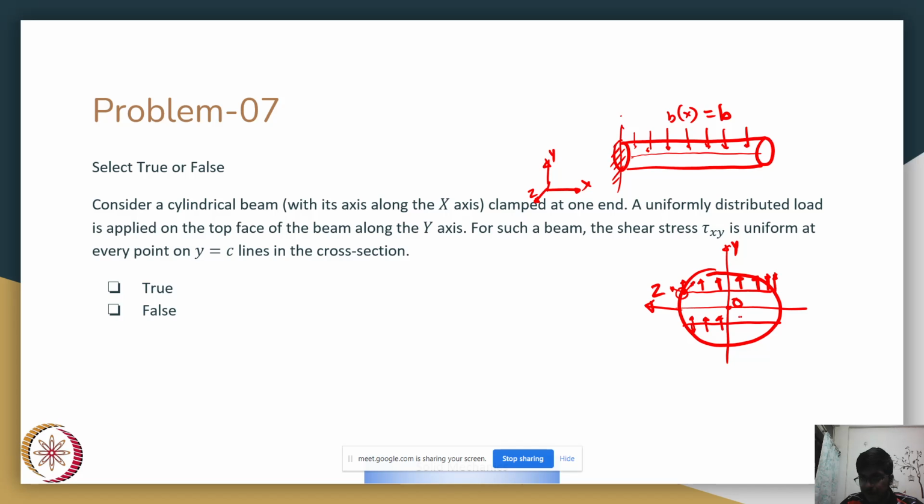shear values, and if they are all of the same magnitude, you can see that right at the periphery points, say point C and D, you would have a non-zero traction coming normal to your outer surface, which would imply that these points C and D are under some external load, some external traction, which is clearly not the case, because we know that even if there is a load acting on the top half, there is no load acting on the bottom half.